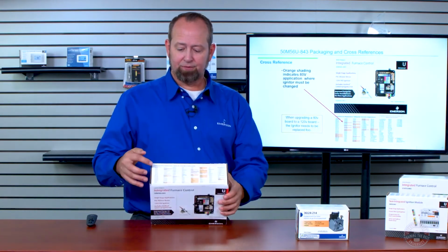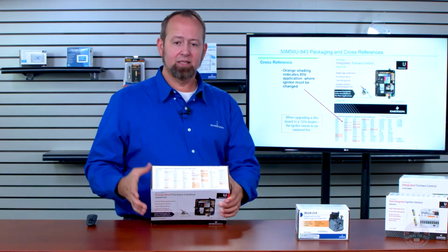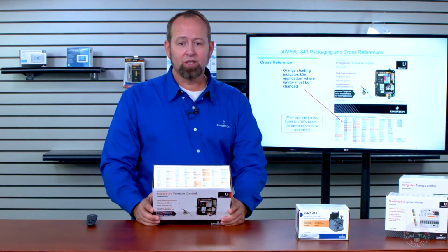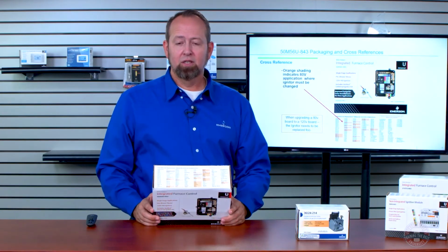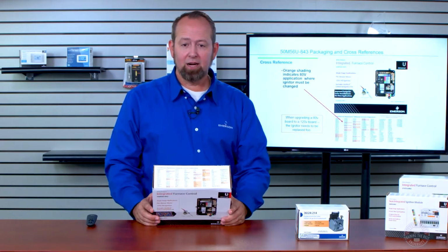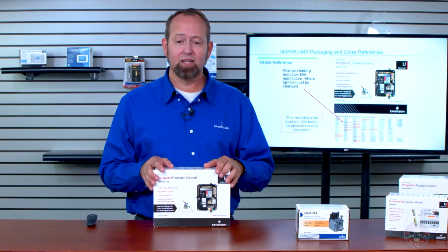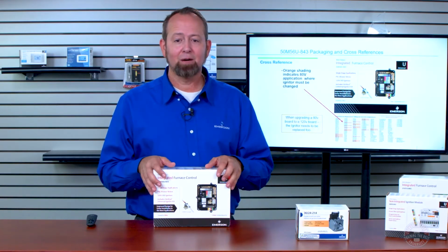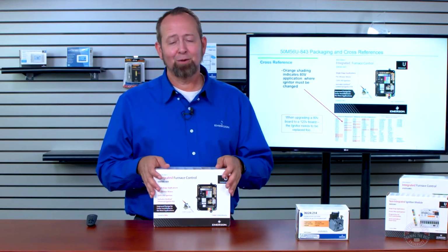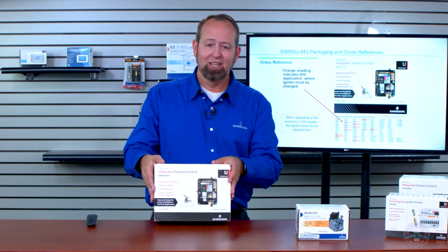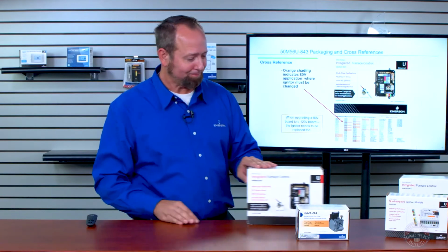Otherwise, if it's not orange, that means the existing board is 120 volt on the igniter, and if it's a good silicon nitride igniter in there already, you may want to save the hot rod for a different sale and make a couple extra bucks on it, or you can help the homeowner out ensuring that they got a new 5-year warranty part and replace it all at the same time.